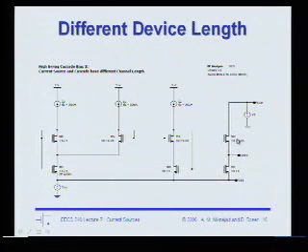And this is actually something that's very often done, right? You don't necessarily want to size your cascode device the same as the bottom transistor for frequency response reasons, for noise reasons. And so here, this circuit lets us get a shorter channel length on this cascode device.